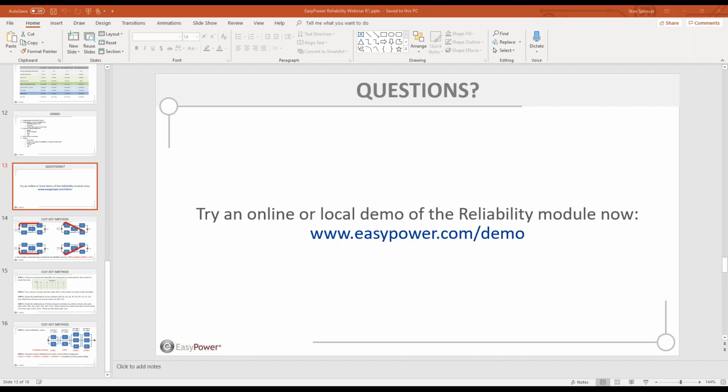It's all averaged in. The other point I'd like to make is that the assumption we make in 493 is that the failure rate is based on an exponential distribution. What that means is that the failure rate is constant. So whether the equipment is brand new, I just installed it on the floor, or it's 1,000 years old, my failure rate's the same. Is that real?